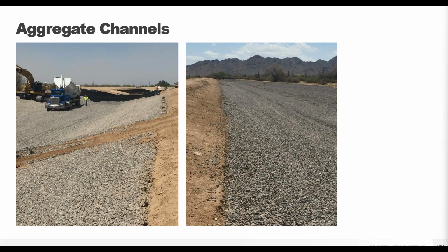The advantage to GeoWeb aggregate channels is construction equipment can drive on the GeoWeb areas immediately after infilling. So again, you can use the GeoWeb channel as an access road for construction, as you see in the photos here.